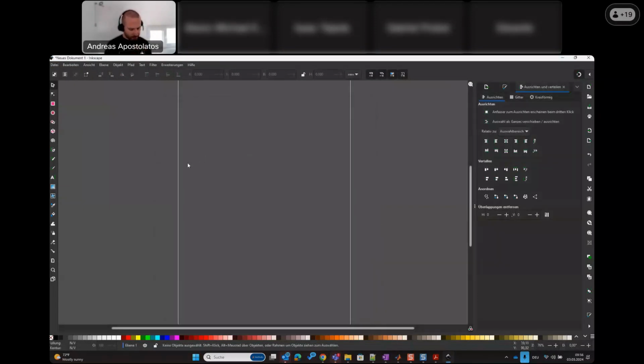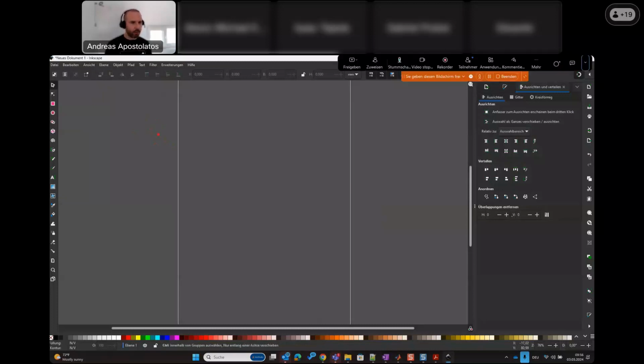So what we typically have to do here is that, firstly, we have to evaluate a derivative of a quantity. Let's call it u, with respect to the physical space, right? That's the first thing we need to do. And now we know that this quantity, it doesn't matter what it is, it might be the geometry description itself, it might be a field that we try to approximate. This will always, in the case of the parametric geometry description and the isoparametric elements, be dependent on the parametric space psi, right?